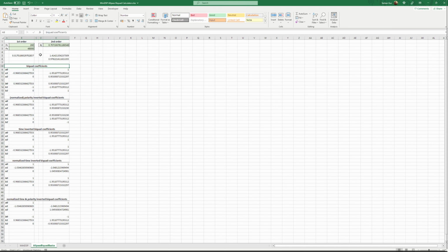And for second order, there must be a quality factor, bandwidth. This number here is the square root of 0.5, 1 divided by square root of 2. This is the Q coefficient, very commonly used. So I have a copy of it here in case you need it, quite precise. So for the first order all-pass filter, which you will use for 12 dB per octave correction, all you need is this constant here, tangent of pi times frequency divided by the sampling rate.